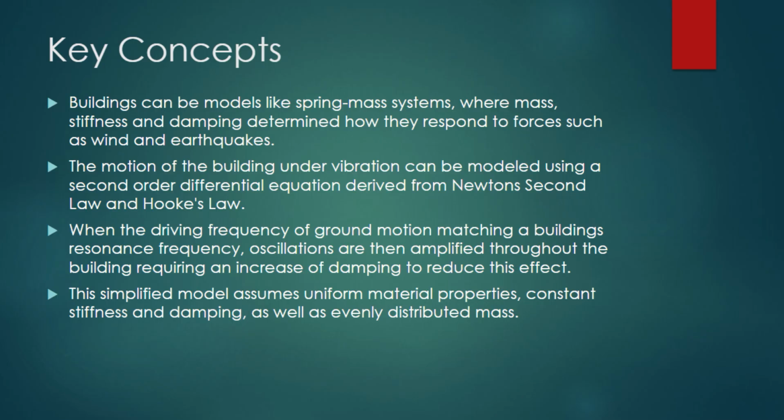Now, the big thing to watch out for in all of this is resonance. If the frequency of the ground's motion during an earthquake matches the building's natural frequency, the oscillations just get amplified. That's when things get pretty dangerous in the real world, because the building starts swaying a lot more than it normally should. That's why damping is such an important part of all this. It helps absorb energy and reduce that motion. We actually see that effect in the math we were doing when we solve the differential equation with a damping term. Of course, our model is obviously simplifying everything a ton.